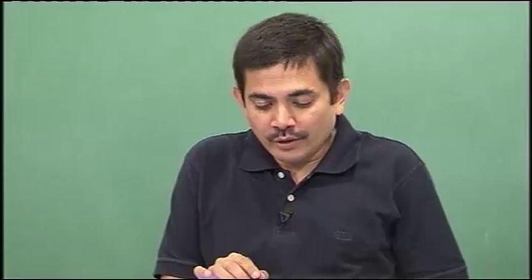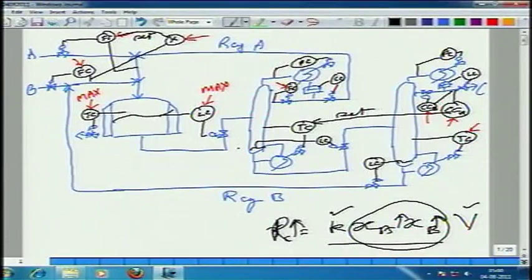The total amount of C should rise a little bit because the generation rate is increasing. So, the molar flow rate of C in the exit stream would increase. You are putting in more total A, more total B in terms of moles, so the molar flow rate of the exit stream will also increase, but the concentration of C would have gone down. But it would not have gone down so much. If you multiply flow and XC, that component flow rate of C would have gone up. That is the extra generation. That is how you are getting more production. Does that make sense or no?